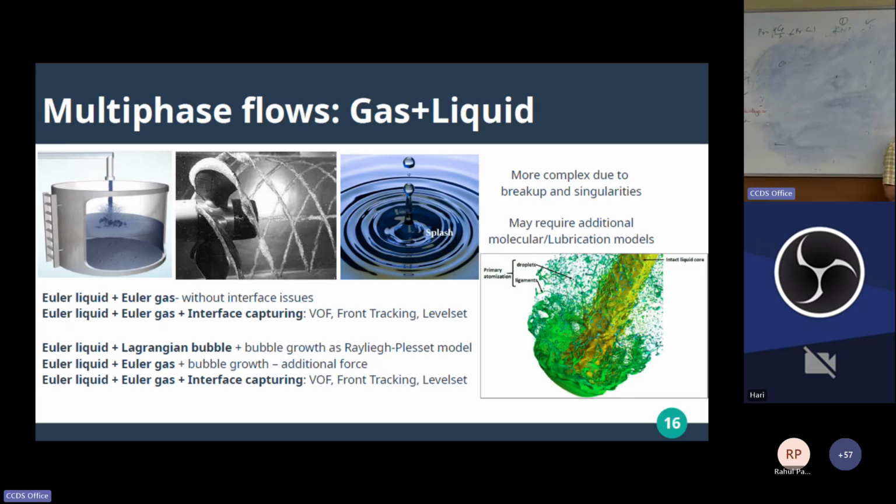A variety of structures like ligaments, interaction, droplets, and immediate evaporation happen. And this kind of simulation, just one spray on supercomputers, goes for at least 1 week to 10 days on 1,000-core systems. People really worry about what is the best solver, and whether it really resolves and helps to understand this breakup in engine sprays.